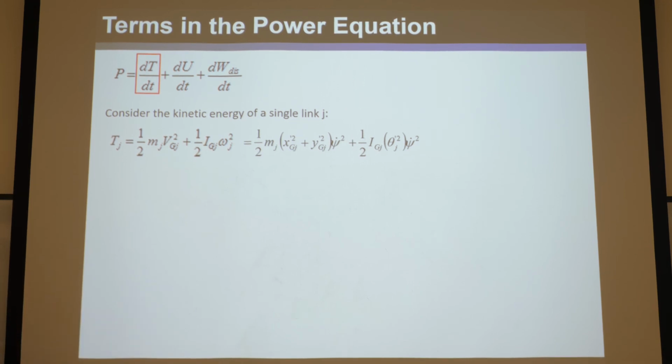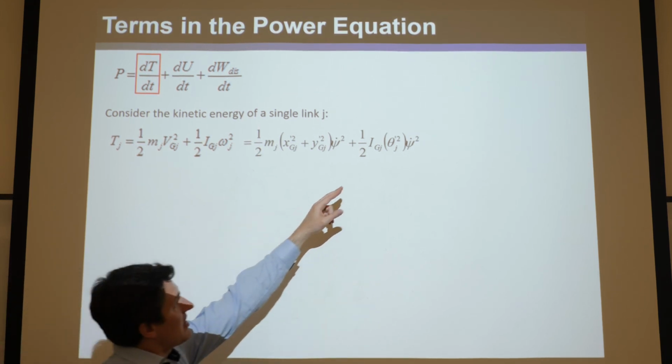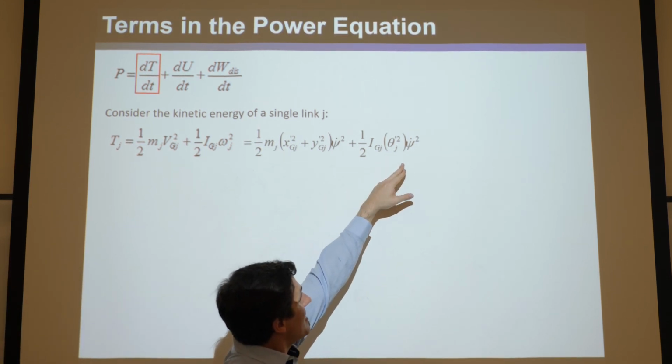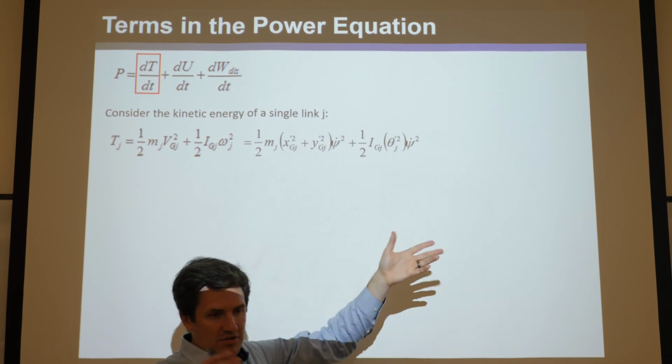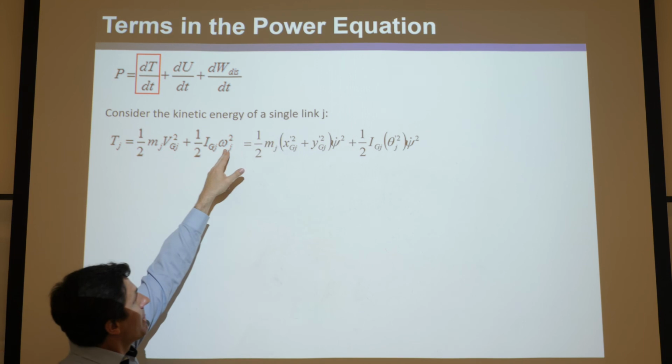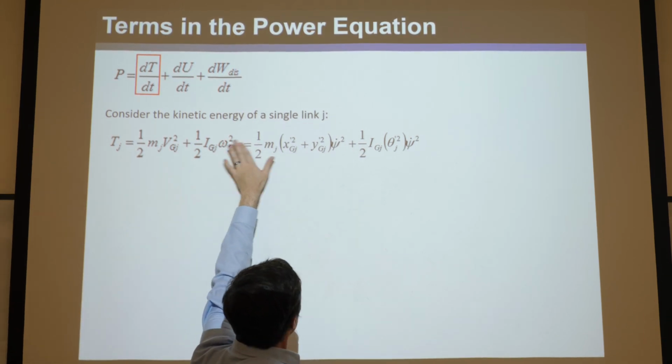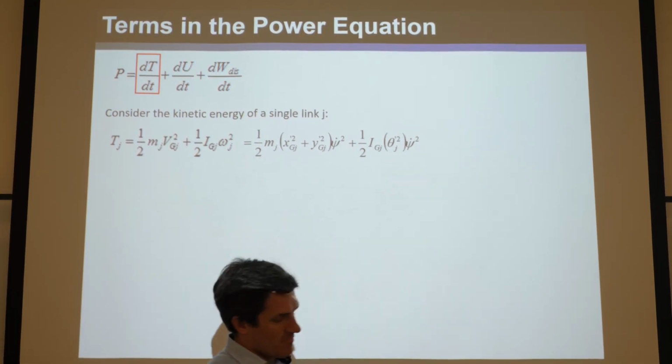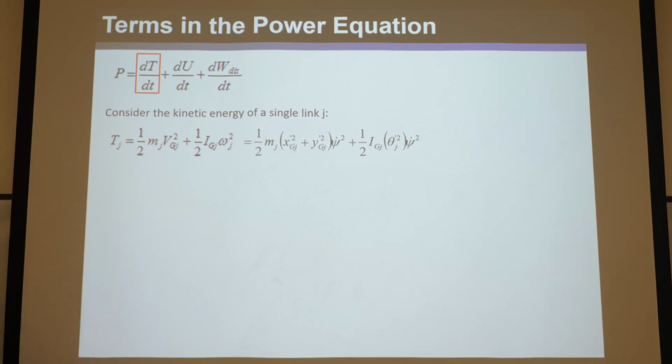Because it's a planar scenario, it just has one component coming out of the page. And if you take the first order kinematic coefficient of theta and multiply it by the input variable, whether that's a rotation or a translation, it doesn't matter, that'll be the angular velocity, and that's what's squared. That's this guy. So hopefully you can see omega j squared is this from previous lectures. So that's kinematic coefficient land.